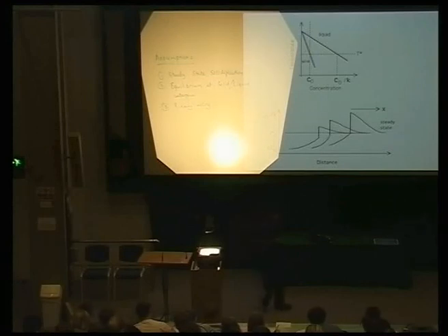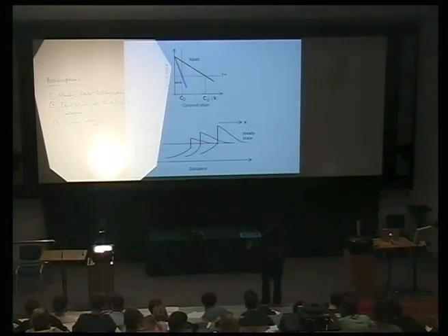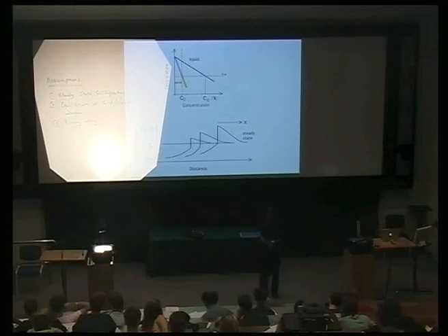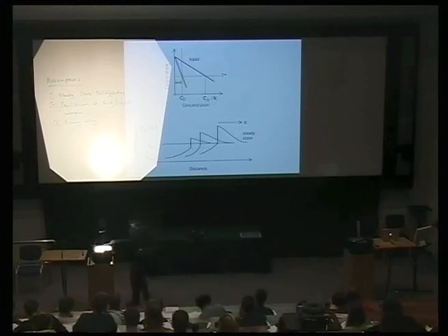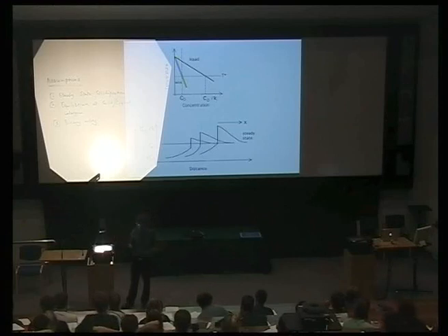So these are important assumptions. And although this equation will be valid for many scenarios, it will not be valid for most real materials where we have many, many different solutes, and solidification may not be steady state, and the solidification rates that we force on materials might be so large that you will get deviations from equilibrium.